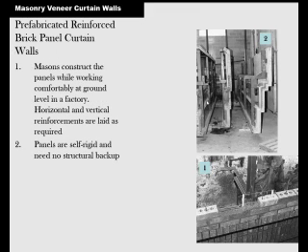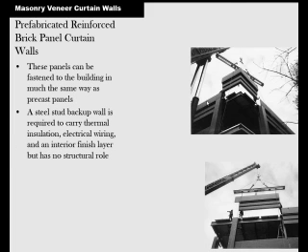Here you can also prefab your masonry. It can be brought to the site just like in that movie, and they can just hoist it into place. And there's a lot more control, obviously, in the factory if you can build it there. If you've got a repetitive form that can be used over and over again, that's a good way to do it. There you can see them putting a corner piece on what looks like a parking garage, perhaps, and then a flat piece as well.